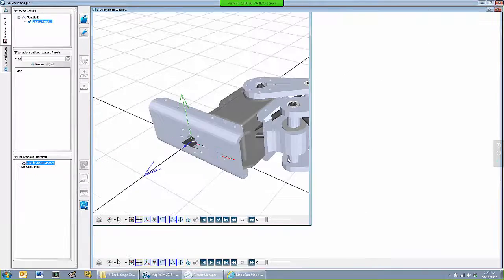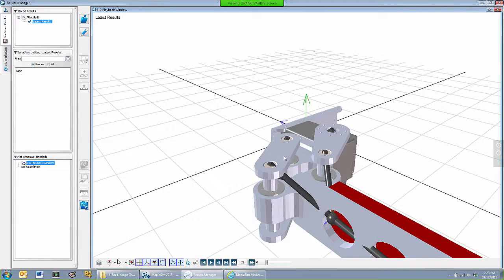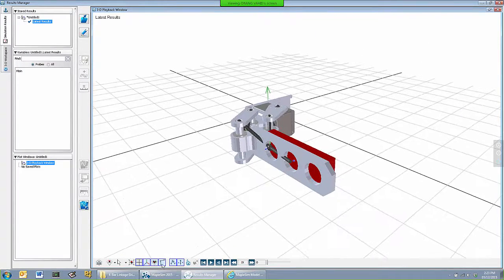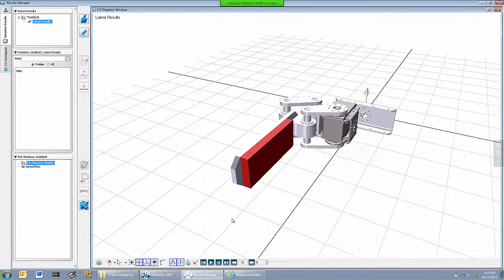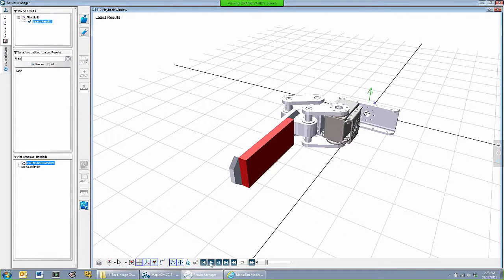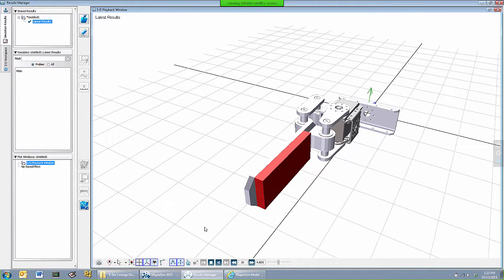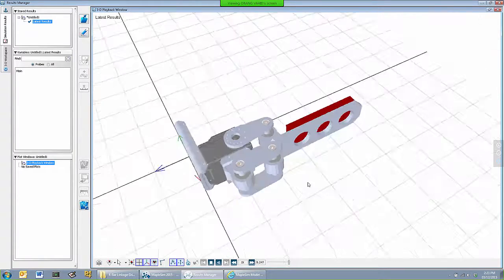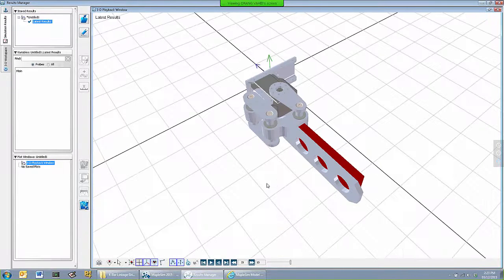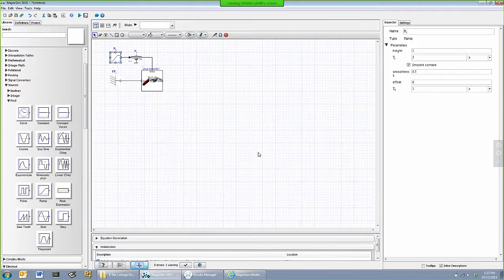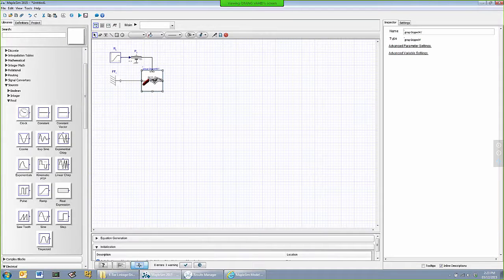Let's make this full screen. Turn off the primitives in MapleSim for visualizing the objects and run the simulation. So one finger moves in a direction that we want. Basically, half of the gripping action is done. So we can finish the model in MapleSim by making another copy of the model. So I'm going to copy this.